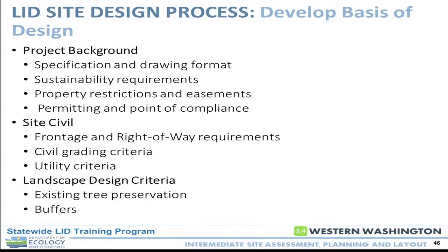The next step is developing the basis of design. What are you going to design to? Get that down on paper early on in the project so you can understand and everybody knows exactly the assumptions you're going to apply on these projects, and so you don't have to come back later and reiterate to achieve a new design requirement that you didn't know about early on.